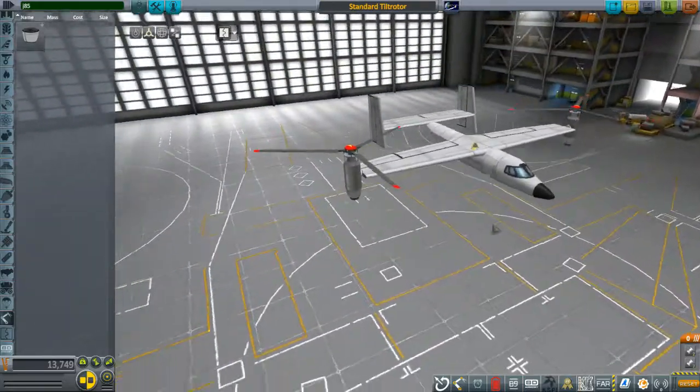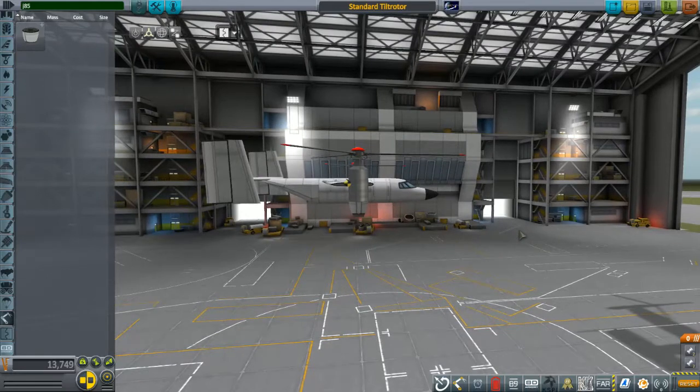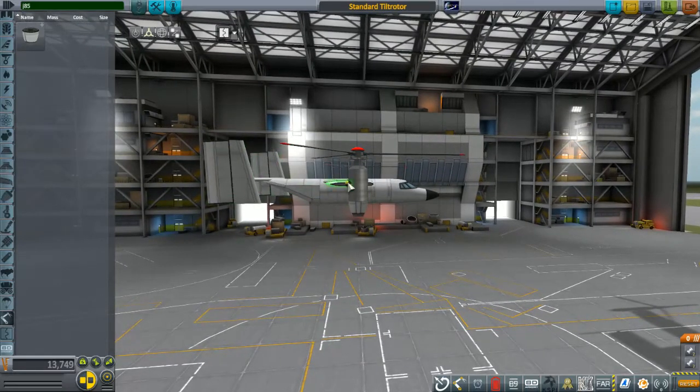The reason for this being that, as you can see, if these rotors are pulling up, they are actually a lever on that center of mass sphere. They're going to pull up on the front, which means the back of the vehicle is going to try and drop, which means you have to counter with other control forces. The more you got your center of mass right between the rotor blades, the more it's just going to pull it straight up. If the center of mass is too far forward, it goes the other way.